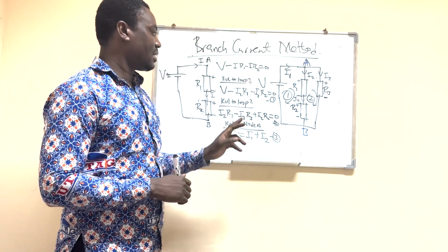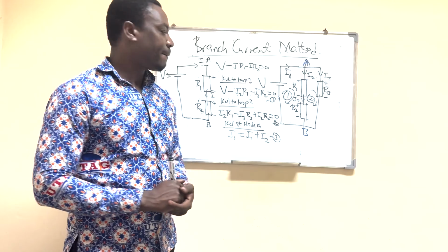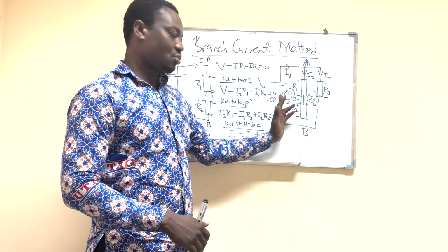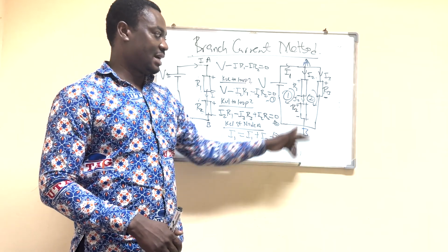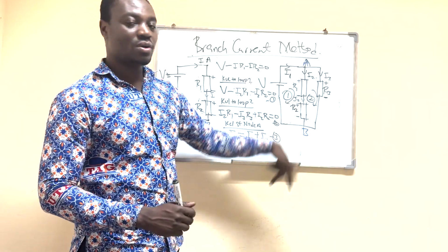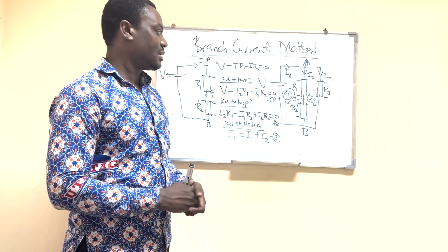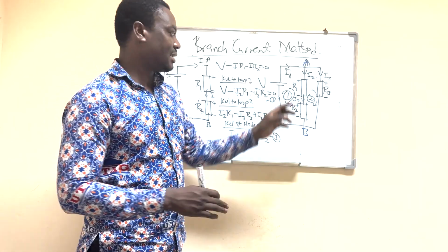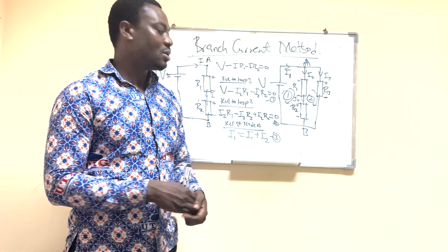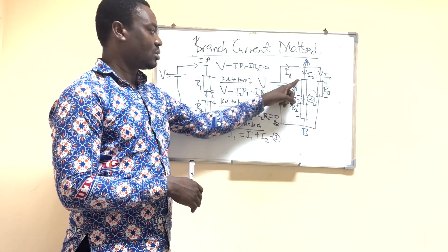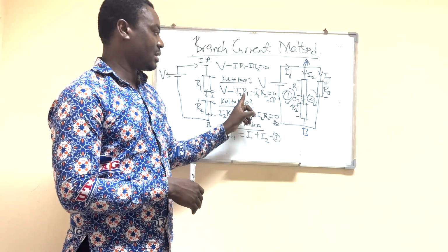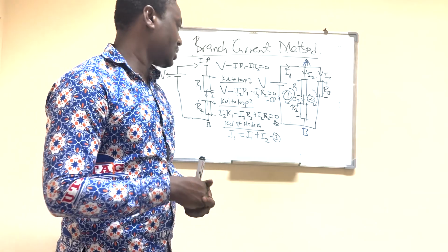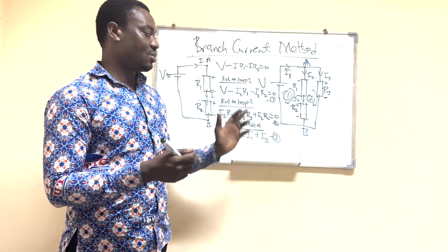So here, with Kirchhoff law being applied to loop 1, what do we get? Again, we choose the direction. We have loop 1, we choose the direction. I always move clockwise. So here, when you move clockwise, you see that minus to plus is rise, and then all the resistors here you get drop. So we have V minus I2 R1, see, I2 is entering R1, minus I2 times R2 equals 0. So that will give us our first equation. You simplify this and label it as equation 1.